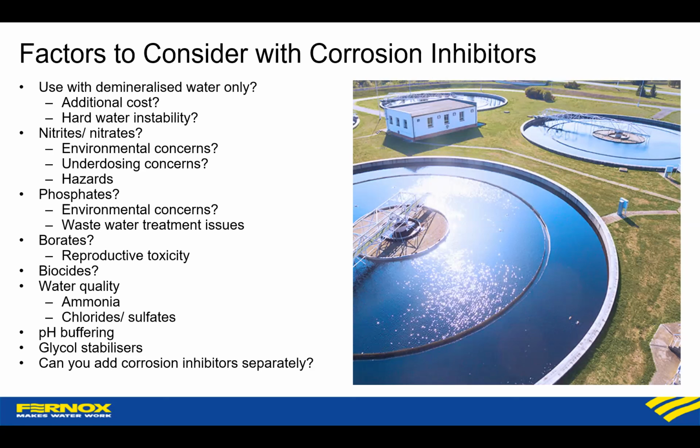You can either use a product which doesn't specify that, or there may be an additional cost or additional time on site to produce the deionized water, and it may be something to look out for. Any product which does say it can only be used with deionized water, just have in the back of your mind that that's probably because it's not stable in hard water.